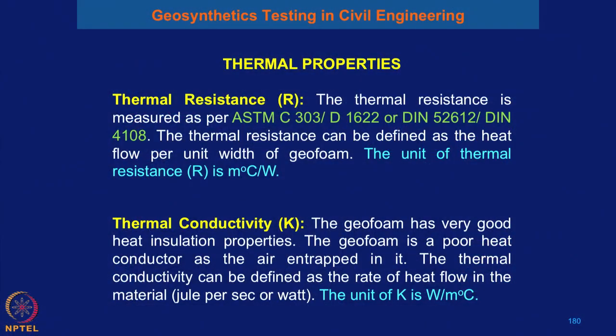Now, as an alternative to this system, you can adopt the EPS geofoam material instead of the gravel, and you can observe what the difference in temperature will be, and how much wattage you can save. I will show you that with one example. But first, just to know the thermal property, the thermal resistance of the geofoam material.